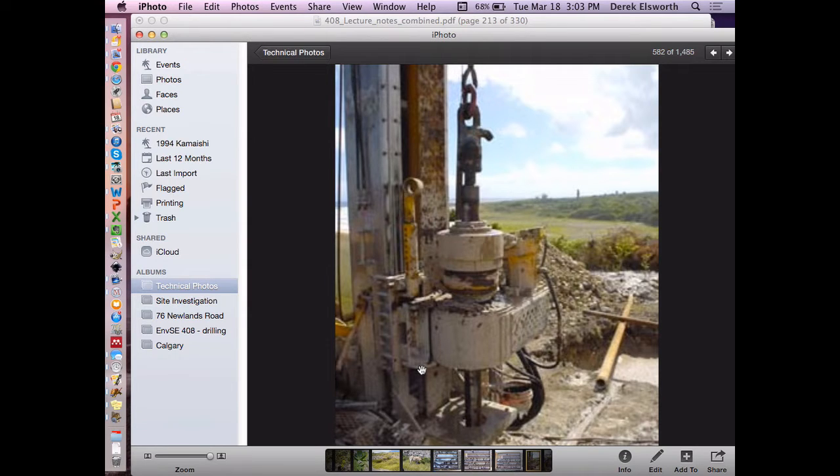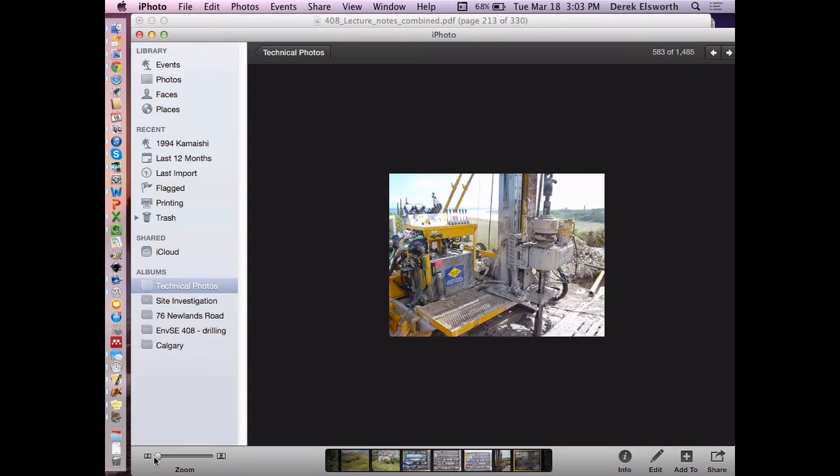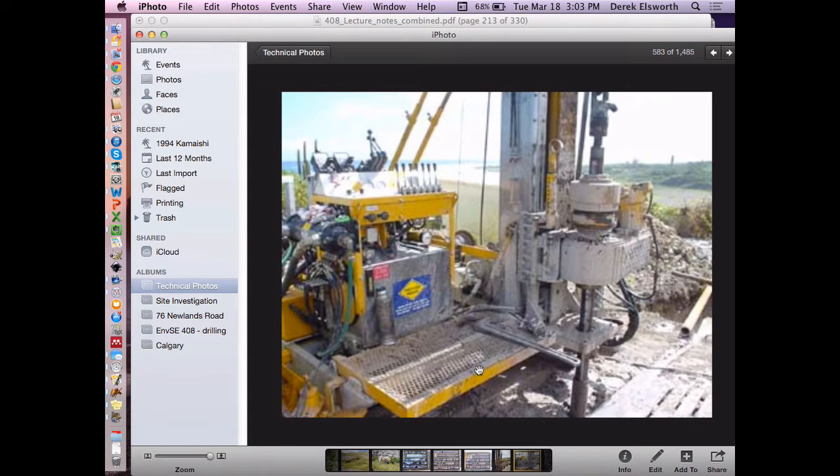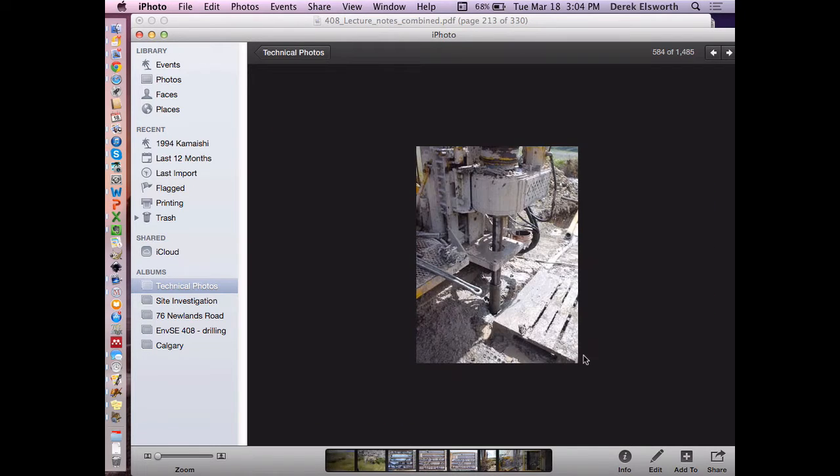This happens to be a wireline rig. So you can see the same assembly here. This is going into some casing, which just keeps the hole open. There's water coming out. Actually, probably not much water coming out from this casing. This is a hole with lost water, which is bad because your bit gets hot and gets stuck in the hole if you lose water. But this is partway on its travel down to the bottom.